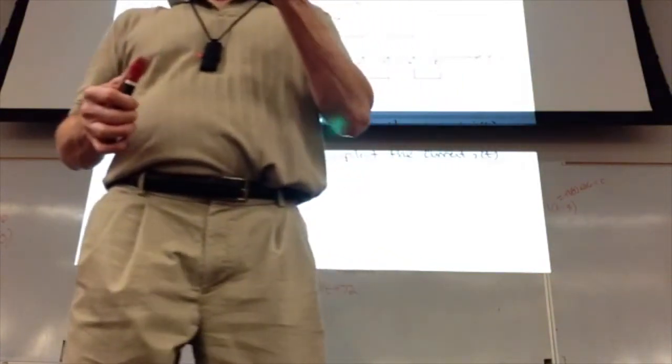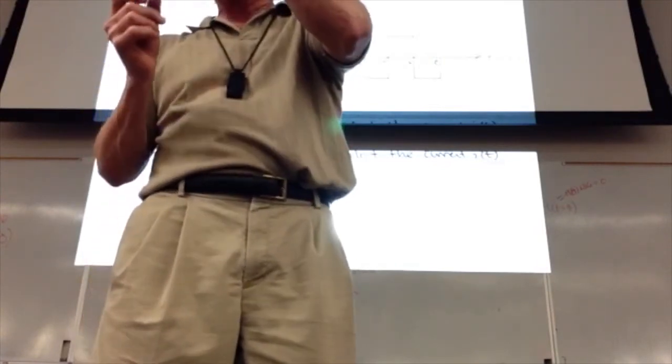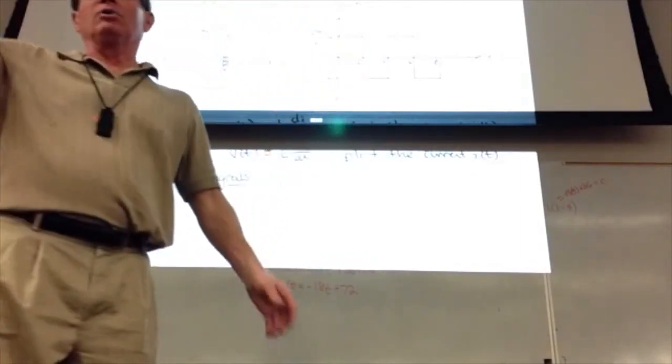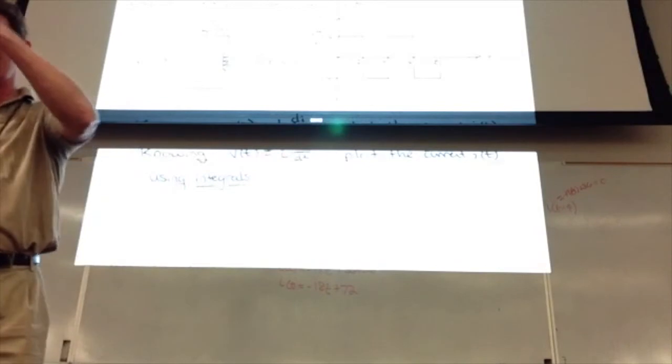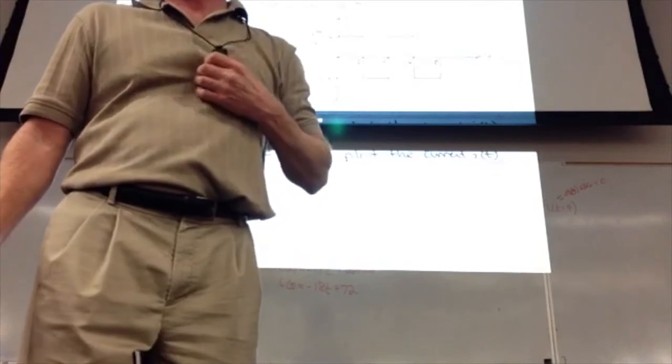So this is 18t minus 4. Okay? And that's valid for 4 less than t, which is less than or equal to 6. It actually comes from the physical principle of an inductor, that the inductor current cannot change instantaneously between one little time point and another. So right before I get to 6 and right when I'm at 6, it's still valid. That's a very good point, though. When you get into calculus, you can make the arguments a little bit more refined here.